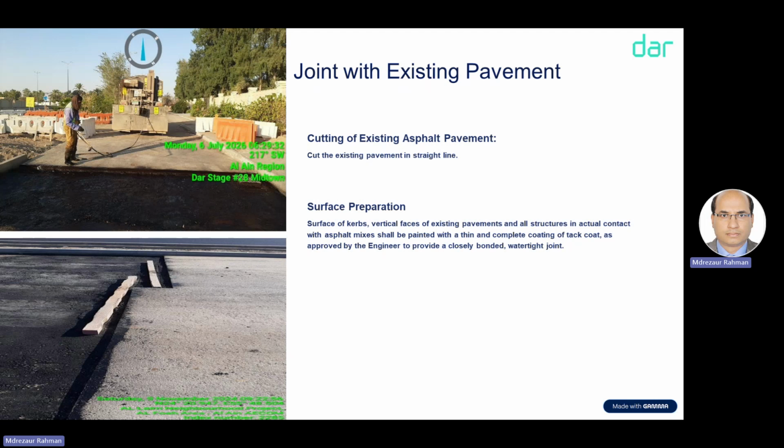In this section, the visual, there is another one for horizontal. The overlap is different. No, we are not considering road base. Road base, generally you can have the same joint. If the road base joint is here, we cannot do the asphalt joint in the same place. It should be minimum 2 meters, either going or coming back. Okay.